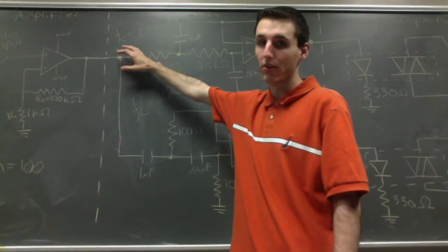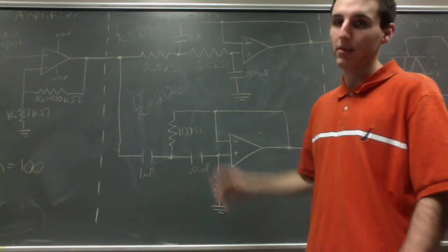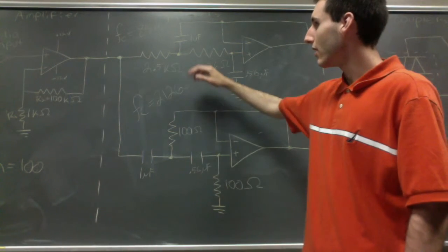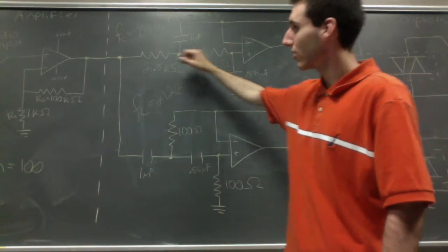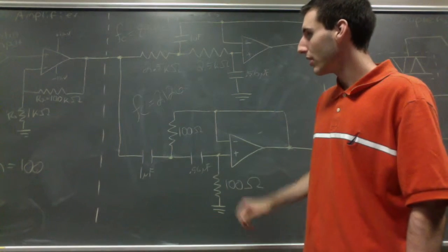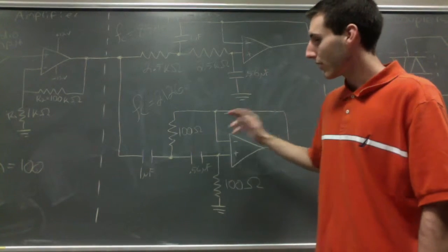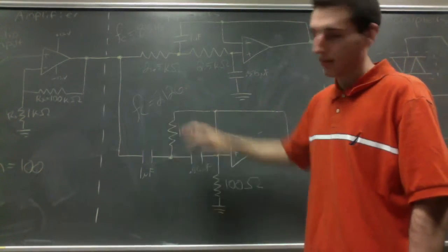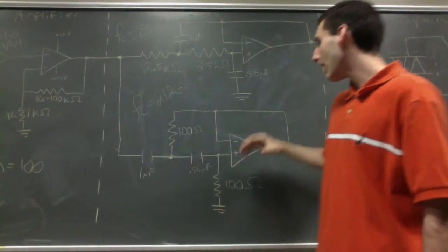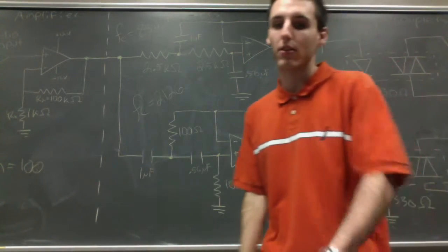The second subsystem of our circuit is the low-pass filter and the high-pass filter. And our audio signal is coming into both filters. The filters are connected in parallel. That way they're not both operating one after the other. And we scaled our low pass filter to a cutoff frequency of 85 hertz. And we did that by changing resistor values and capacitor values. For our high pass filter, we have a cutoff of 2,126 hertz. And the output of these filters goes into the optocouplers and the triacs.